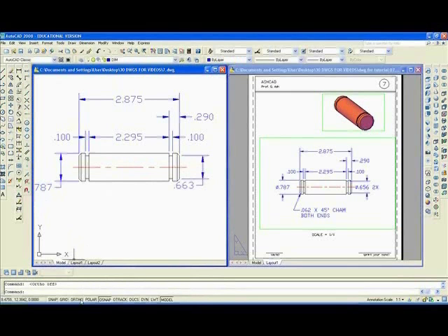In the meantime, what I'm going to do is take off ortho, take off OSNAP, and I'm going to erase this dimension because the numbers are obviously wrong. And so I'm going to redimension that. I'll pick from the endpoint or intersection right there to the other endpoint or intersection right there and drag it out. Okay, now I'll click on that and then move it up to say there. Hit escape.